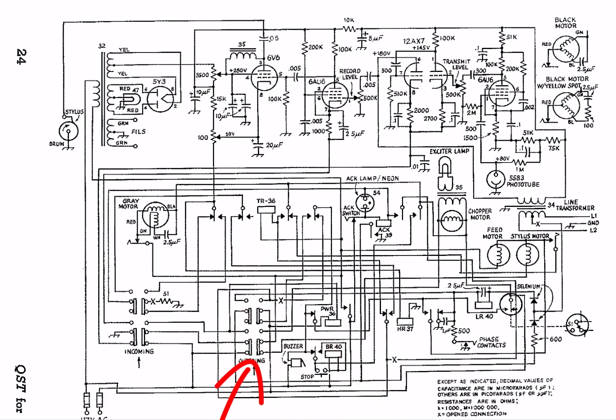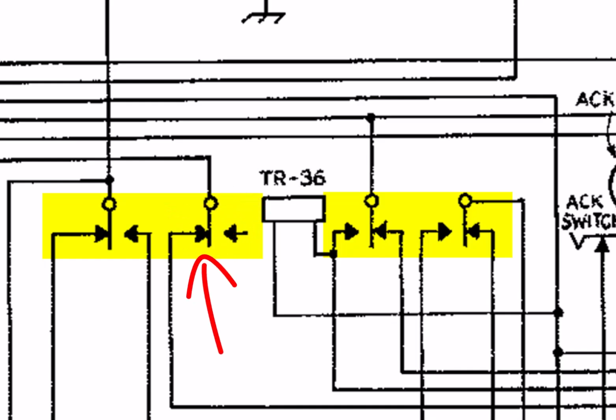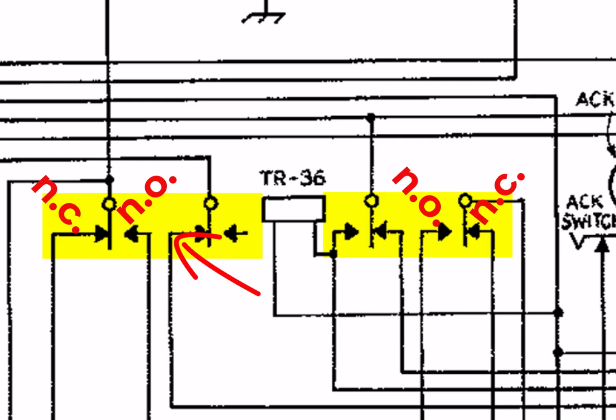Now they've drawn the schematic so that the normal position, the non-energized state, of all the contacts are away from the solenoid. When energized, the reed is pulled towards the coil. For many of the coils, they show contacts on one or the other or both sides, wherever they're convenient to the schematic, but in all cases, the terminal that's further away from the coil is the non-energized state, the normally closed state. And when the coil is energized, the reed moves towards the coil to that contact.